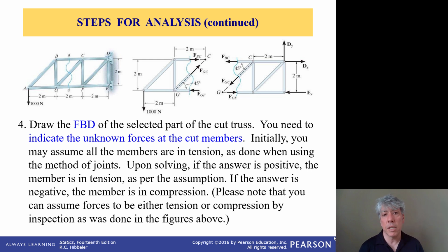You'll notice in the example here that F sub GF has been drawn as a compressive load rather than tensile. And so if you know for sure that the load will end up being compressive, then that's probably okay. But to build good habits in your homework, you should probably just draw all of your forces as tensile forces on all the members and let the math work out whether it's actually compressive or not.